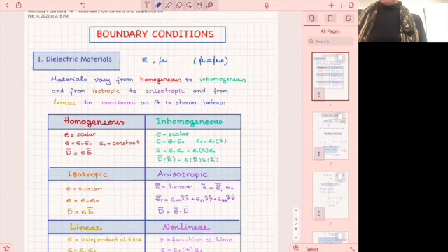And then if your source is complex and you can make it up from different pieces, then you can use superposition. In fact, you can use superposition for the fields, all right? So you can take each part of your source separately. If you have the formula, you can use it, and then you can sum up all of the electric fields. That's what we found in the homework, all right, with a square.